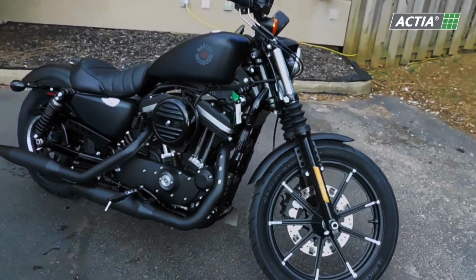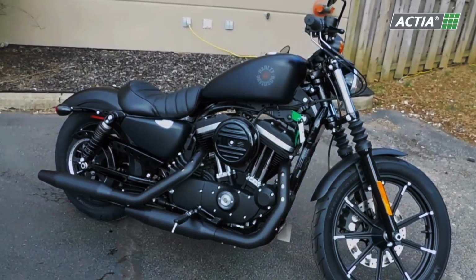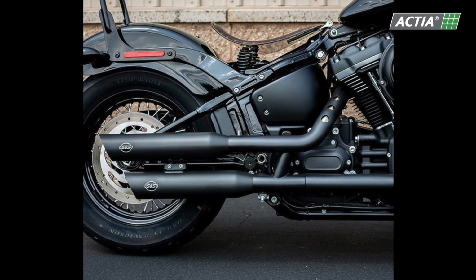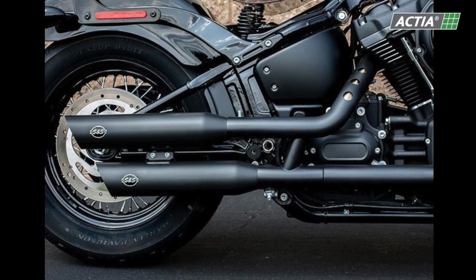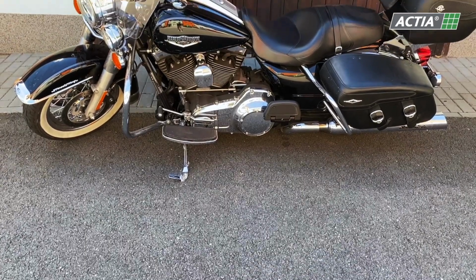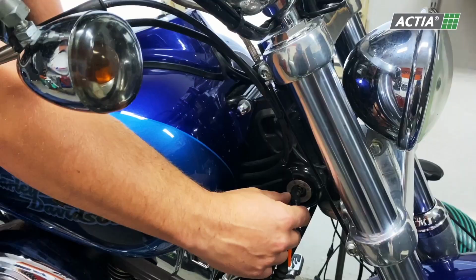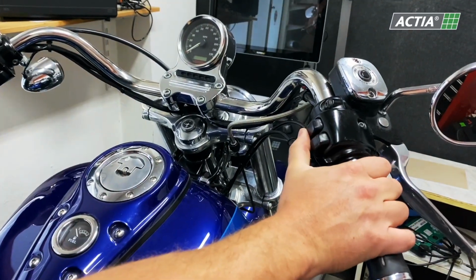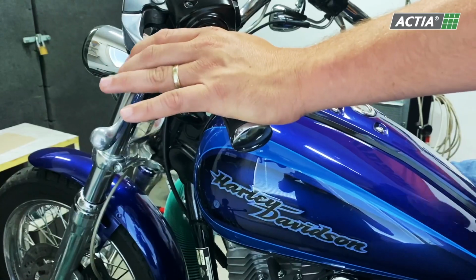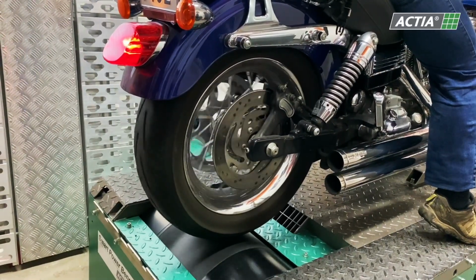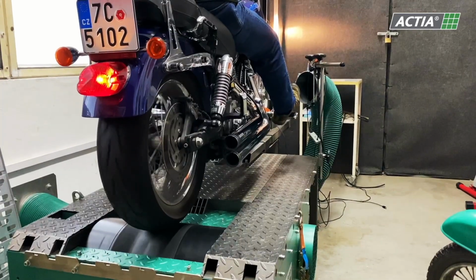The stoichiometric air-fuel ratio is a ratio where the engine has minimal emissions and operates at more or less minimal fuel consumption. Maintaining the stoichiometric ratio in these areas is also important for proper functioning of the catalytic converter, which is then able to nearly eliminate the engine's already low emissions. With this, we have described the design of a motorcycle as it comes out of a factory.